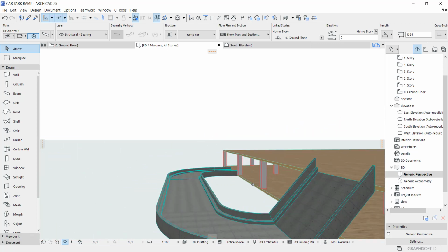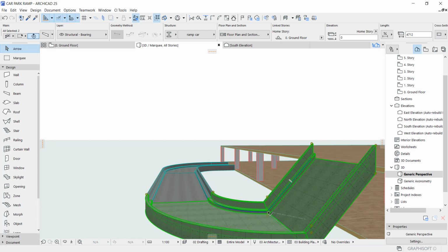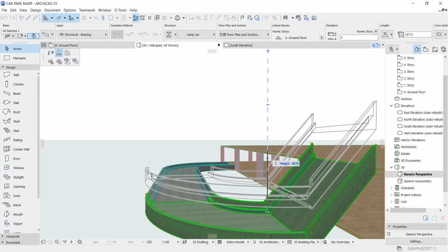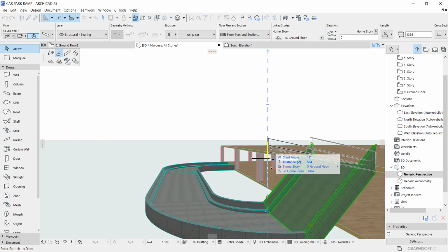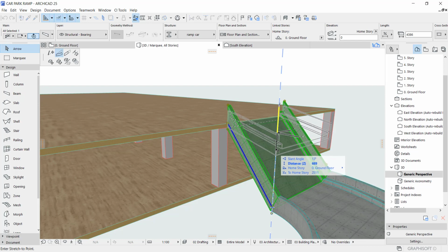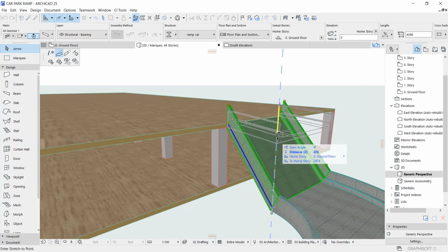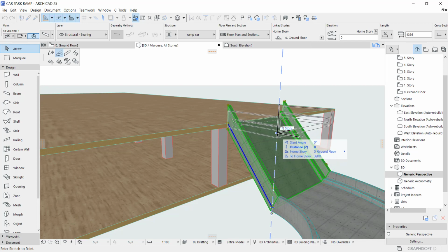Now from our transition we did with the rail tool, we took this up. I was going to pick both points, but you can't. So I'm going to take this one individually like so. I'll try to rotate to get a better view. Okay, as you can see, it's not showing us the angle of elevation. It's just showing us from the top the distance of transition. And the distance of transition we used for the first one was 200. So I'm going to just go down. You can see the distance, right? It was 200. So I'm going to type 200.